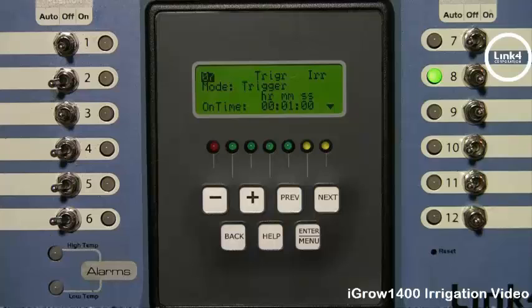Note the digital input has an internal 10K pull-up resistor up to plus 3.3 volts. If the external trigger input is pulled low by an external device for more than 50 milliseconds, then the input is deemed valid.